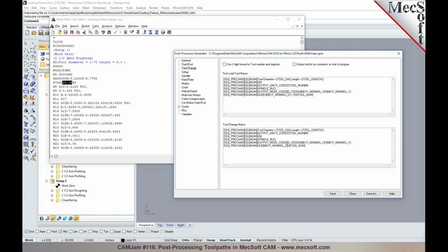So I'm going to say plus 1.0, and then use E to mark the end of the expression. And I'll close it with the bracket parentheses. So I've defined it for the line G43, where the Z value needs to be 1 inch above the clearance height that's being computed. And I'm going to apply the same. I'll just do a copy and a paste for every subsequent tool change as well. So I did a copy and a paste.